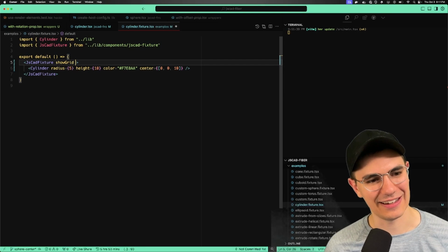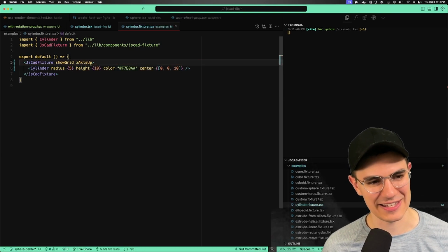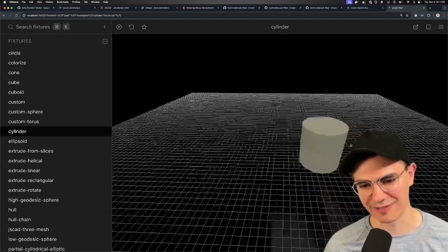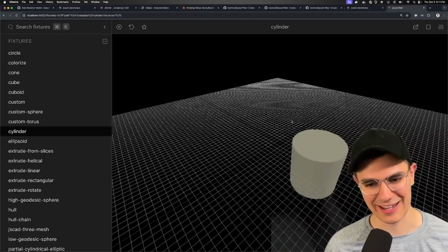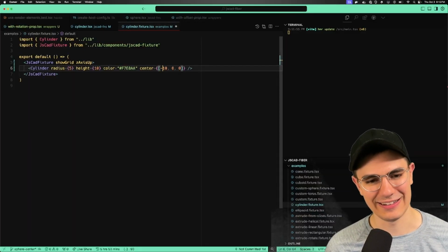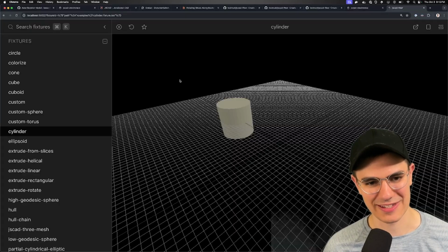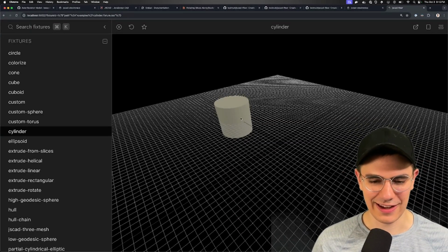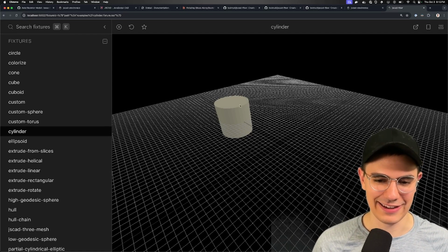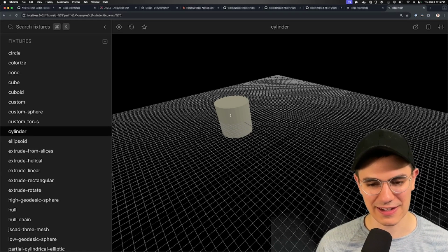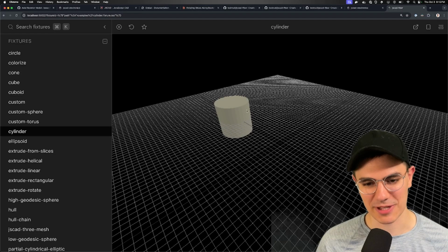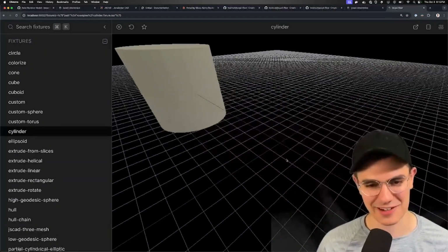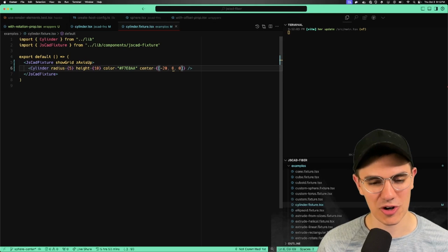I think I'm going to do one last thing, which is make z-axis up on, and move it somewhere to the right, or maybe negative 20, so it's really far over there. Now, when we rotate it, rotation can be weird because it needs to rotate around the center of the thing, and often when you rotate something, it doesn't rotate around the center. That's why I moved it, to make sure it wasn't in the center, because otherwise we wouldn't know if it rotated around the wrong thing.